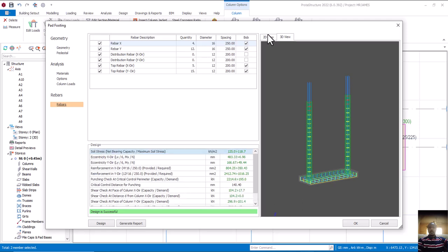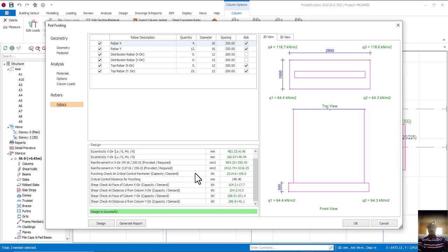So that is that. After which we have checked everything here as part of design. Our rebar is still this one, 16 and all of that. It's okay. Some can use 20, depends on your choice. Is that okay? But for me, due to the issues that we are having with our rebars, some of them are not up to diameter 12. If you use it, by the time you measure it, you discover that you're having like a 10 or 9. And even this Y16, if you go and measure it in the market, some of them are not up to Y16, isn't it?